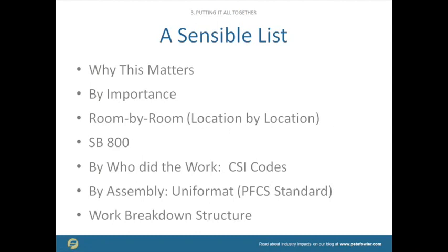regardless of what it's made of, whether it's a plastic shower pan or a mud set tile. It's all going to be inside. In the construction specifications codes, any tile is all going to be clumped together in the same section. So a tile on the outside of the building is going to be in the same section as the tile in the shower, but not in Uniformat. So each has its benefits or its weaknesses. But all of this is a work breakdown structure.